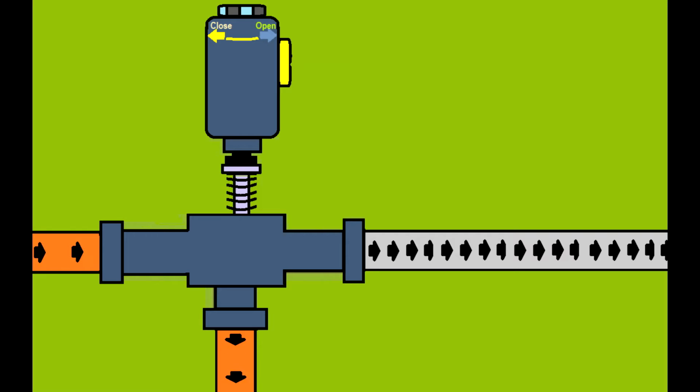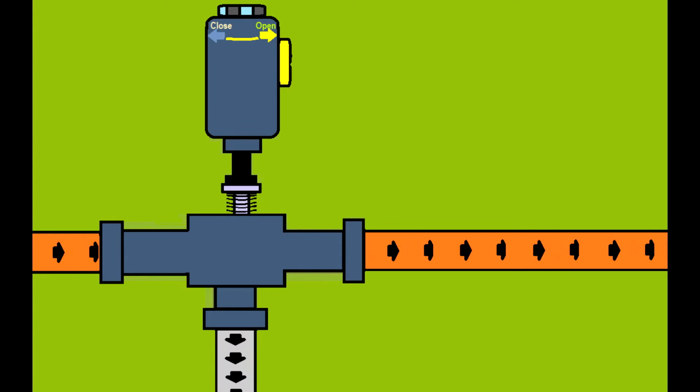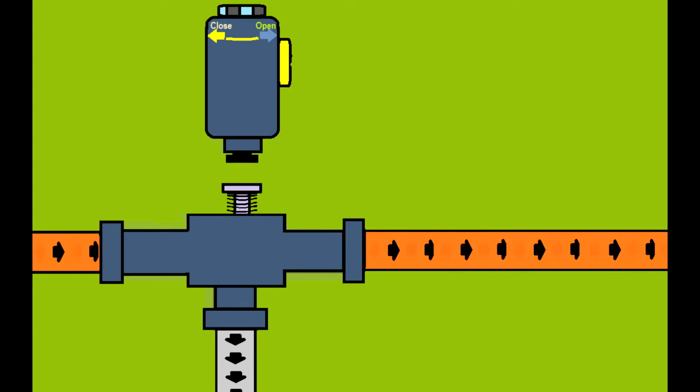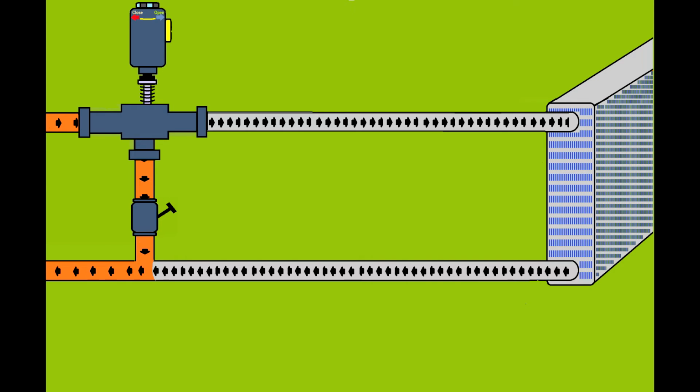Now, this is a three-way valve. It has the capability to divert the flow. So, as you'll see, the valve opens and allows the heating agent to pass by. And at one point, when you try to divert it, it can't, because again the valve shaft is seized and it's not moving. In this case, you will provide heating agent to the heat exchanger all the time. You'll see this again, so you'll see how important it is for the valve to work.